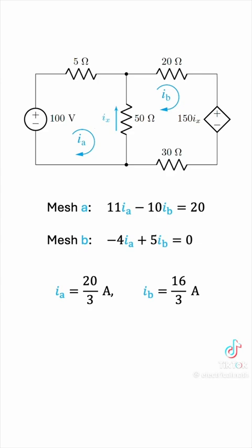In general, we have three equations for power: voltage times current, the square of the voltage divided by resistance, and the square of current multiplied by the resistance. When you want to find the power associated with a source, you can only use the first equation because you don't know the resistance of a source. So you should always multiply voltage by current.